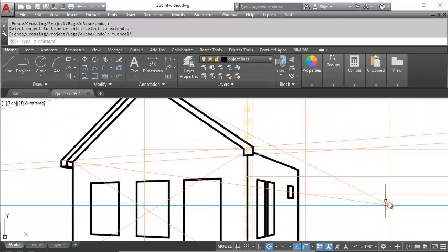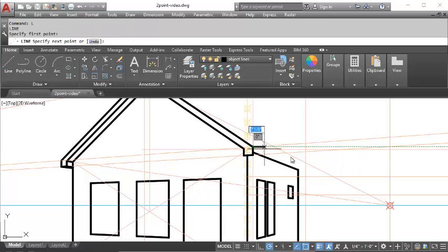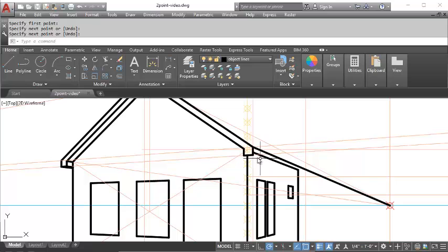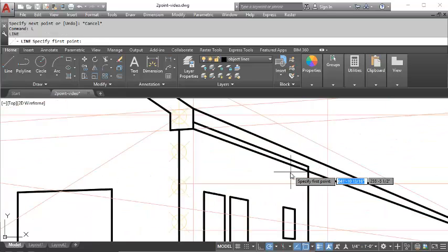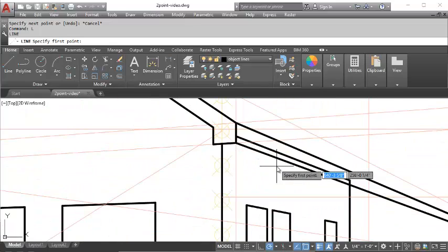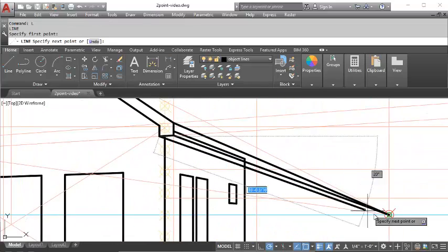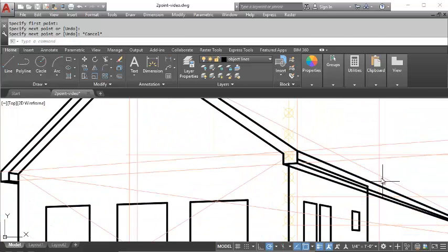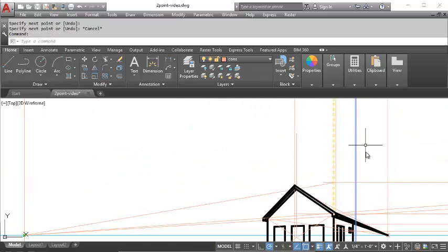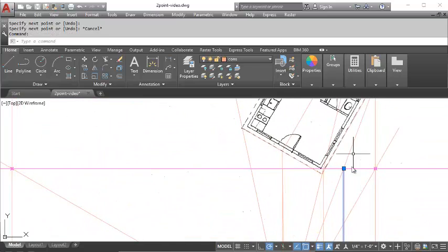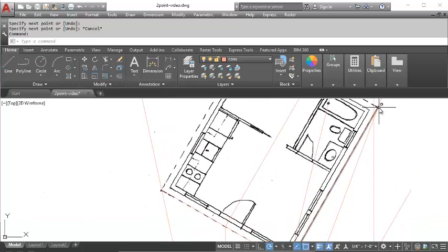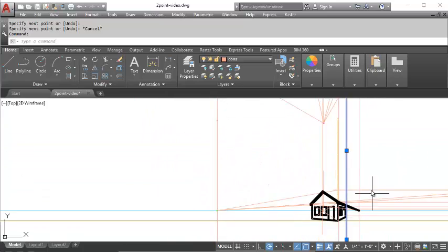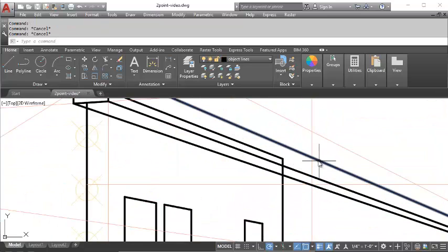And now to define this fascia on this side, we use the line command from the corners we've defined. And we'd also want to draw a line from this edge back so that we can see how much of our soffit is overhung. Now this is where this line comes into play. This line, remember, is defining the edge of the roof as it appears from the station point. That's where the edge of the roof is. So all of this soffit information stops there.